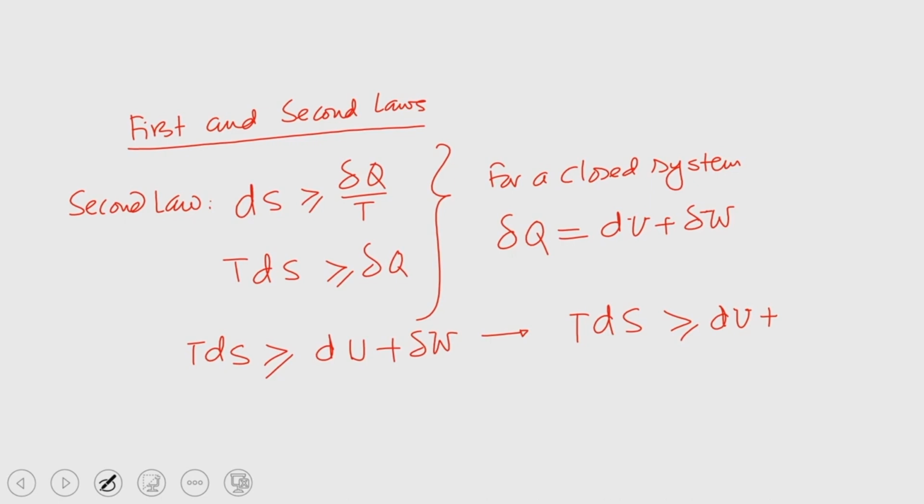That is a substance in which only the changes in pressure, volume and temperature are considered, rather the work done due to mechanical, electrical and magnetic effects are not considered. So, basically if it is a simple compressible pure substance, only the changes in P, V, T are considered, and the effects stemming from applied or induced electrical and magnetic interactions are not considered.